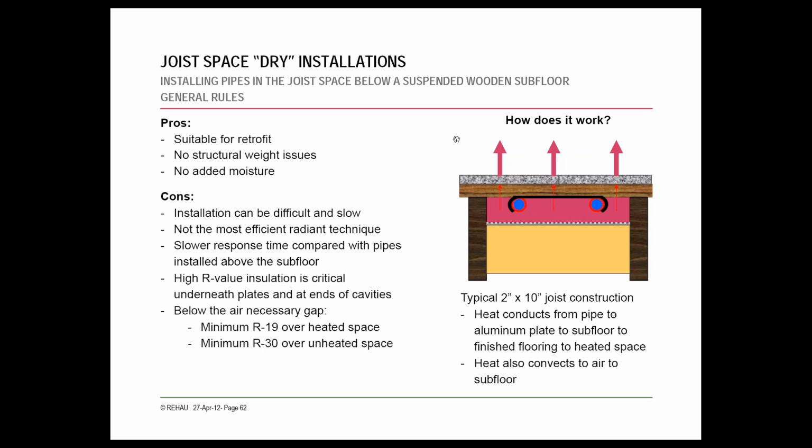The other word you might add would be lower costs, because this does have some cost savings compared to a wet installation, but in general, we reserve or recommend joist space be used in a retrofit, just because, as I mentioned before, you're not going to be able to drive as much heat up through these floors, and it's going to take a little longer for them to recover or provide heat.